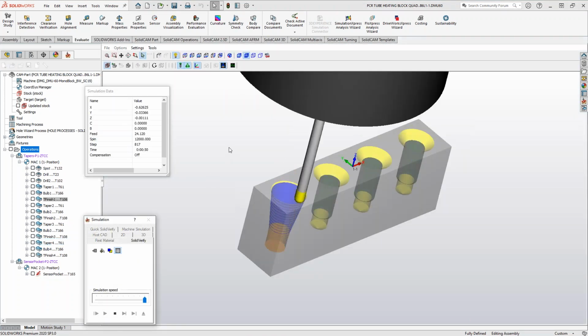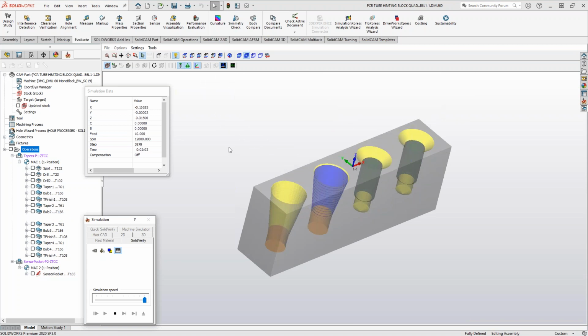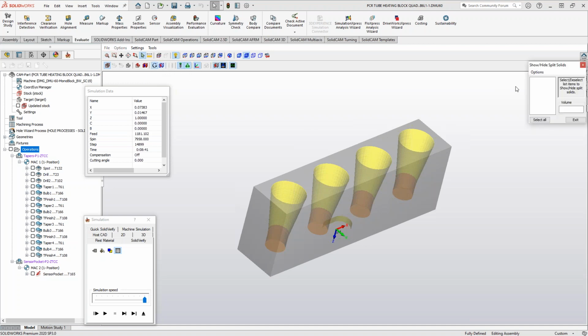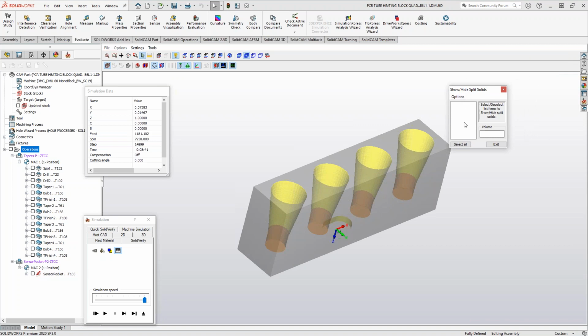Yep. Okay. There is the gouge button up there. It's not one that I use very commonly, but we should be able to turn on and show like a rest material and gouge kind of directly under the settings. Do you see that? One more down. See where the G is? So we can show hide gouges that way, so that turns it on. And then the next one over is we can split the gouges, but technically on this one there's no gouges, so it's not showing us anything.